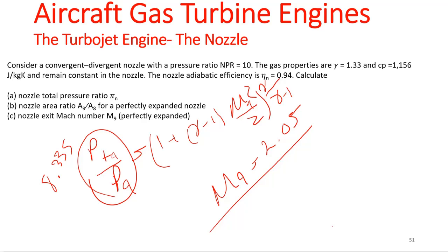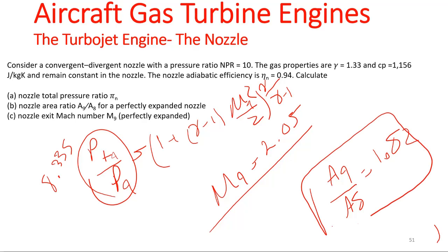So you should be able to start from the conservation of mass between the throat and the inlet, and also the throat and the outlet, and find the properties of the throat. You want to find the ratio to make it simpler. You don't need to find the areas themselves. You just need to find the ratio, and the final ratio is 1.82, right?